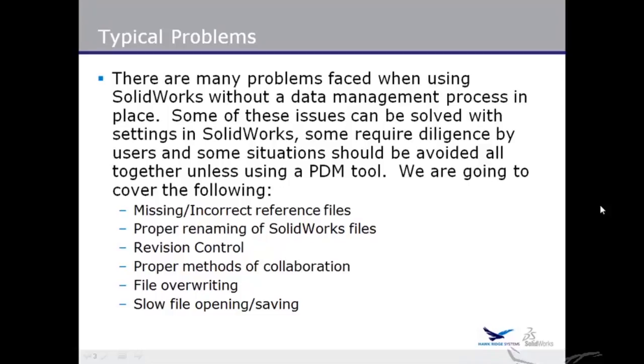That is a very common thing that happens when you're not necessarily managing your references as well as you could be. The other thing is if you rename a file and you open a SolidWorks assembly and the assembly can't find that file now because it's renamed. Very common. There is definitely an easy way to get around that I'm going to show you guys.